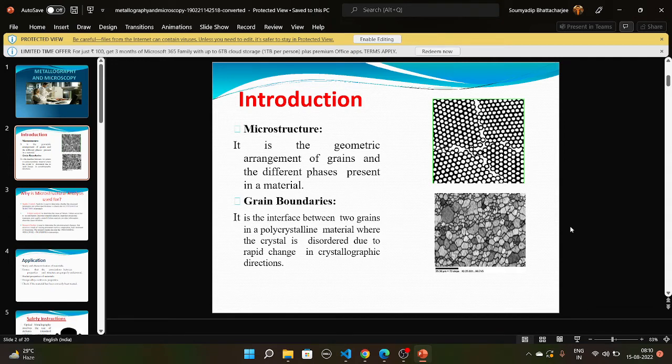So supposing the cutting force is acting on the tool, you can well guess that some forces will come on the tip of the tool. What may happen if you make the tool very hard? It can crack immediately, isn't it? So you have kept your requirement in mind that the tool material should be harder than the job material. But along with this, you have to make sure you have induced some toughness into it, at the cost of brittleness, because more hard means more brittle. A slight force can give rise to a crack in the cutting tool. So you have to ensure some toughness by adopting a proper heat treatment process.